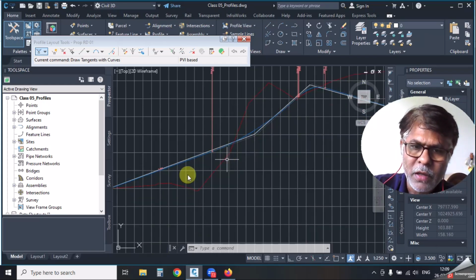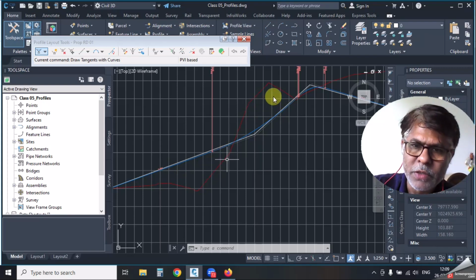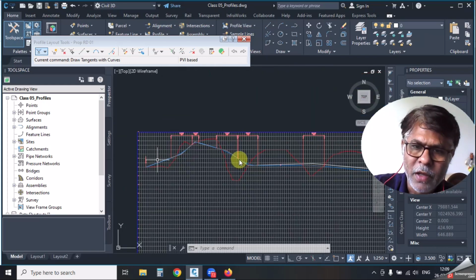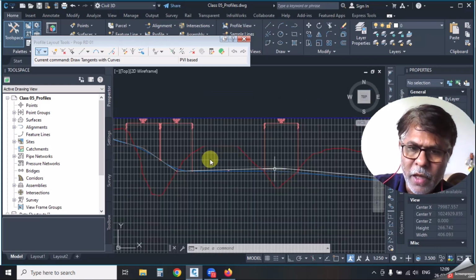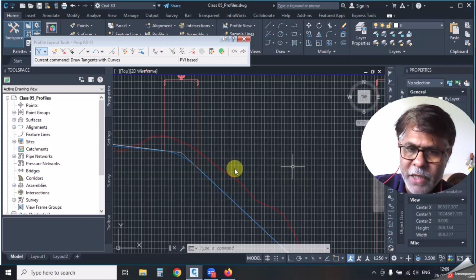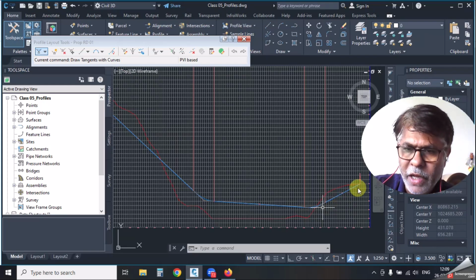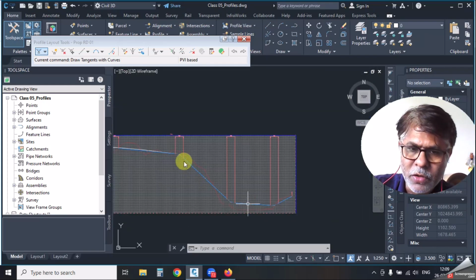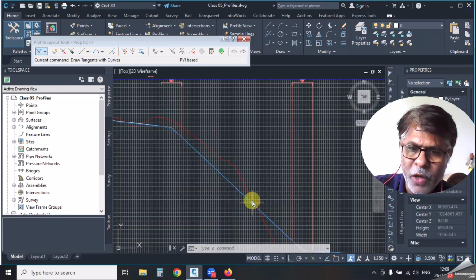See now, here this portion is in fill, that portion is in cut. So I can use this particular cut to fill this area like that. When I go here, I can use this particular cut to fill this area. I can use this particular cut to fill this area, and I'll go on balancing it. I can cut this and fill it here down so that I will get smooth, not very steep roads, and it will be easy to maneuver.